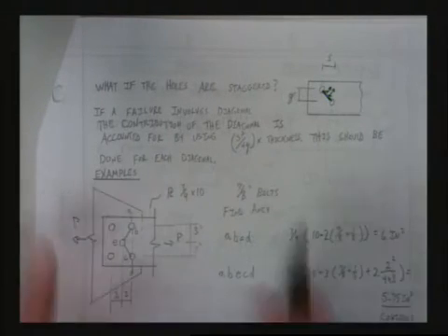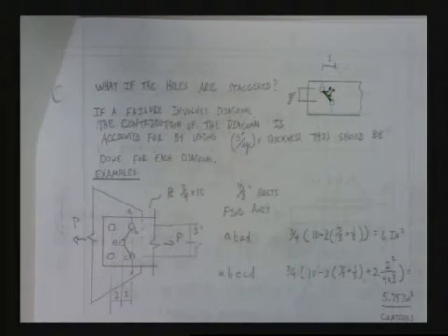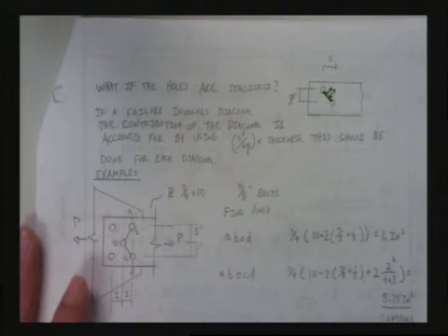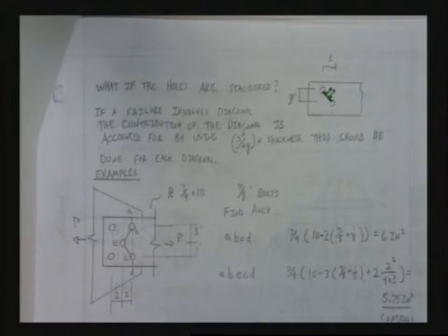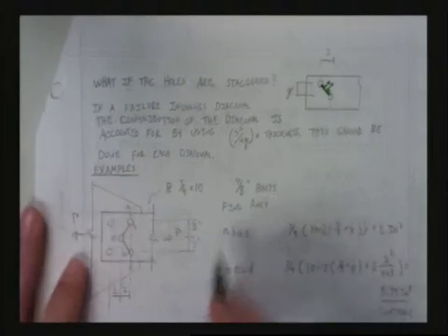Now, you could easily break out a finite element program and figure out the exact answer, if one wanted to. We don't have time in this world. We've got too many other things to do, unless someone's paying you a lot of money to do it. That's what researchers get paid for. Instead, we use things like this s squared over 4g, and it gives you extra thickness, and I'll show you what it means right here. So this is the way this is going to work.